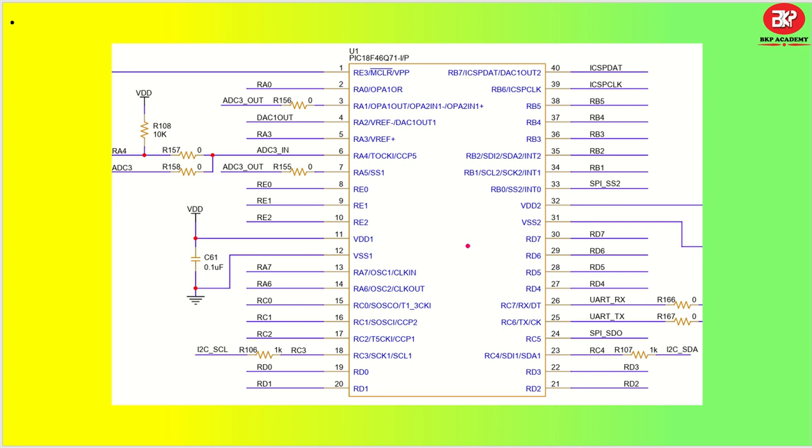You can see, let us say we have to add an ADC input to RE0, which has ADC capability. So what would be the connection? Shall we connect directly? Let us say we have a 12 volt input and we want to measure the value of that voltage. For that, can I connect directly or do I have to do something else? That's what we will learn. Those are the best practices that we will have to follow. So let us see what the best practices are to make the ADC connection properly. In that case, let me just take it here.